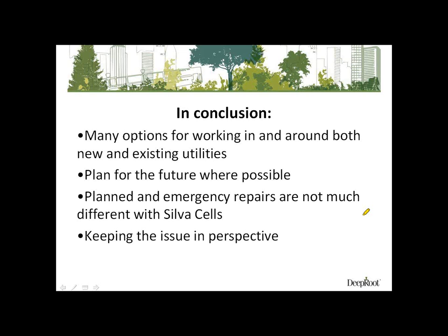Yeah, there's at least one project that comes to mind where we've installed just Silva Cells and no trees, where the Silva Cells are just used strictly as a stormwater treatment device, and there are trees in the vicinity, but there are not necessarily trees linked to the Silva Cells. We've also done an installation recently where the trees will be above and adjacent to the Silva Cells, but they are not actually incorporated into the Silva Cells. I guess a third type of project that we've done, I'm thinking of the Aurora Shoreline project, is where it's kind of shared soil volume and water storage.